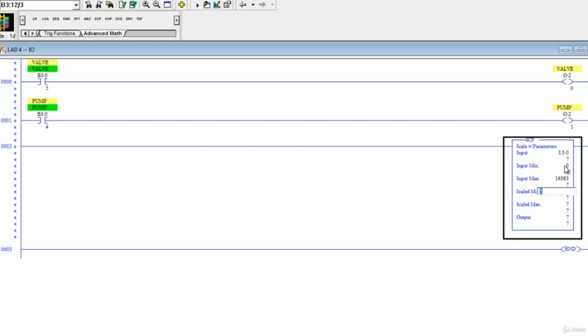And most of the time, unless you're going really cheap on a project, you'll use a level sensor that can be calibrated. So we're going to just go ahead and treat this like 0 to 100%, which is a full tank. And we're going to output this even though we'll be losing a lot of resolution.